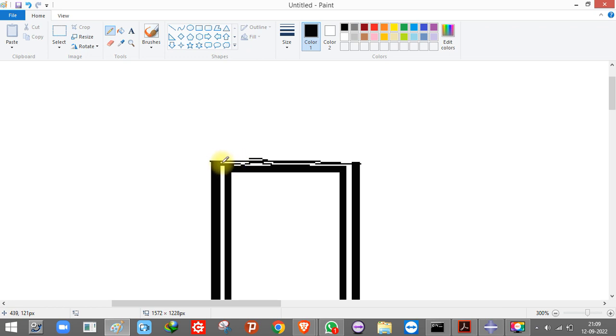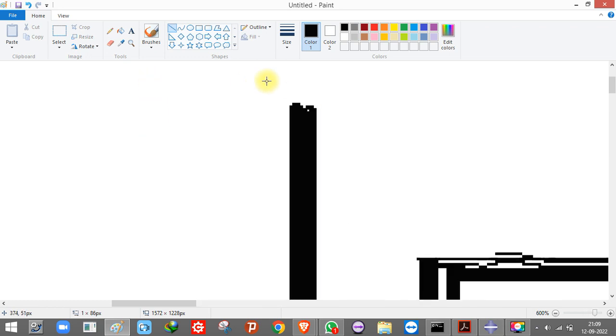due to which you will find that the strong concrete, the concrete which will actually take the load, is available around 1 mm below the steel. Let's say if this is my steel, then somewhere just 1 or 2 mm below you will find that concrete is available. So when you are applying the load using the UTM, the first load is transferred on the steel.